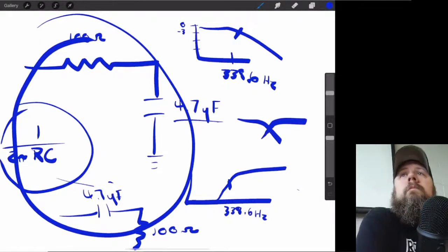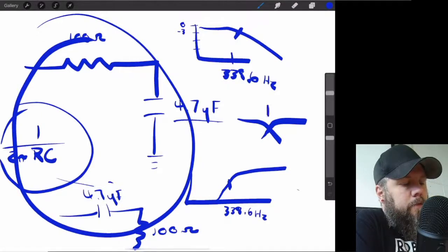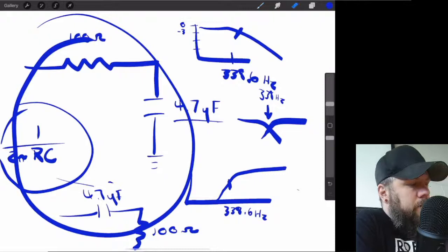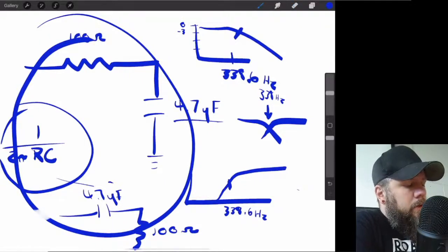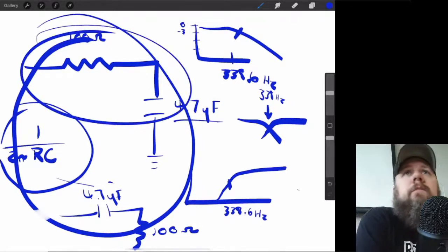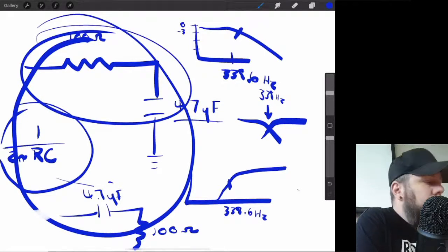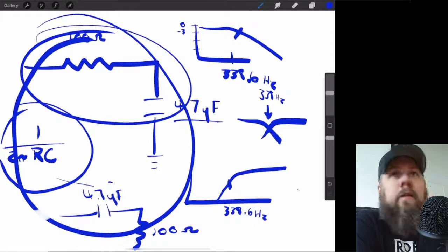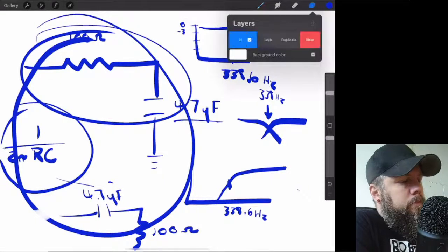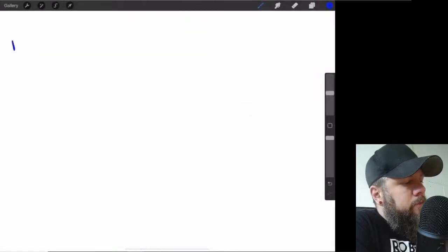Okay? And that means that at this little middle frequency, this frequency right here is at that 338 hertz. Now, I could use this part of the circuit down here to go out to my tweeters. I could use this circuit right here to go out to my subs. Okay? So I put an input on both of these, and then, well, let's draw that real quick. So I have my in. I've got this weird waveform, right?